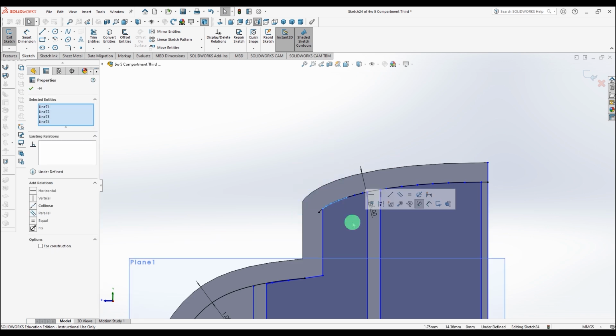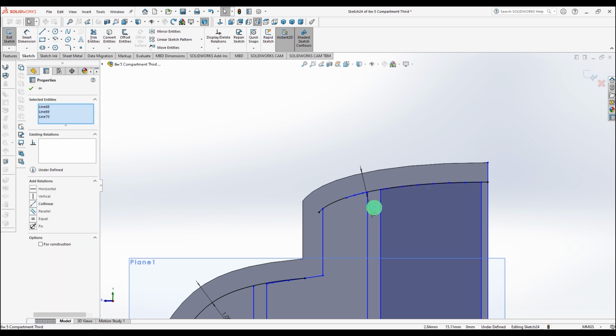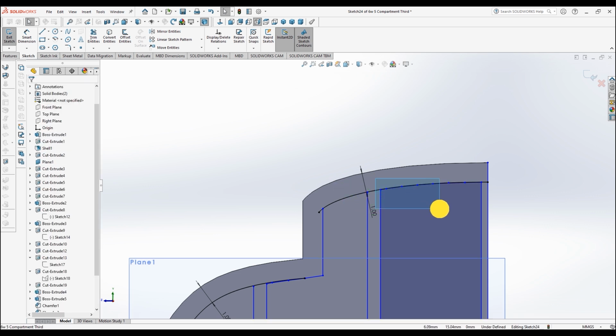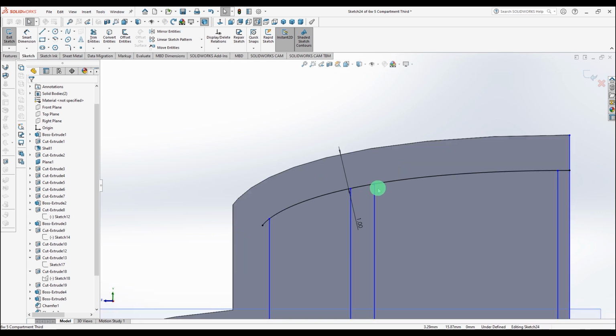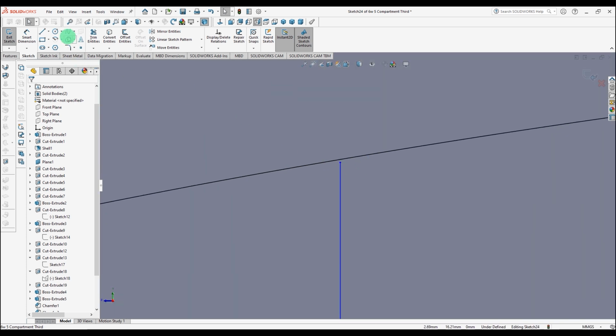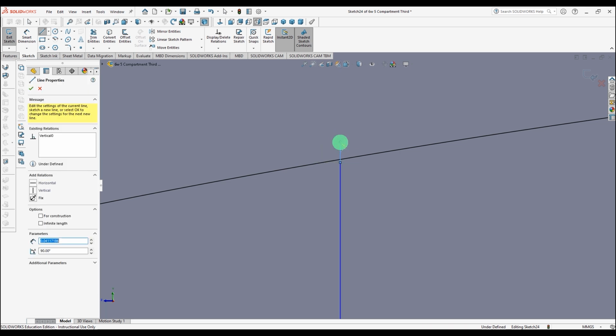I'm doing the same up the top, and this is just as you may remember from the first video of this two-parter. I don't like the splines as they are generated from my 2D CAD software, so I'm basically just copying those with a spline in SolidWorks.